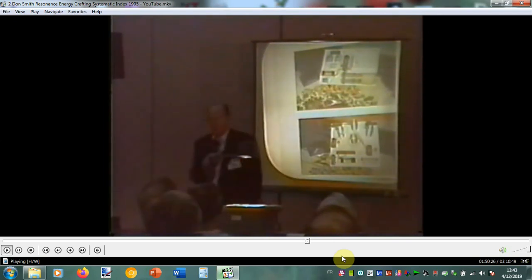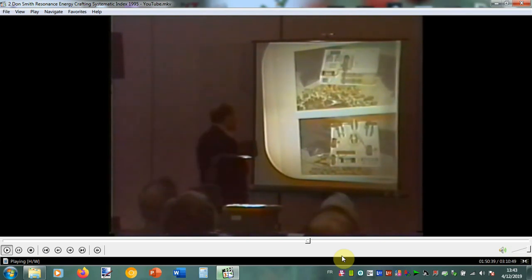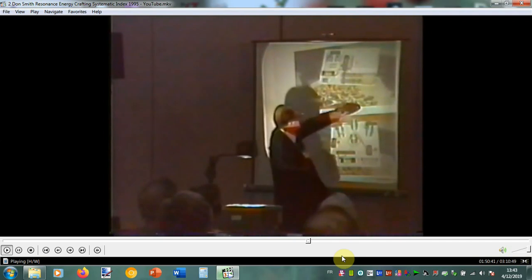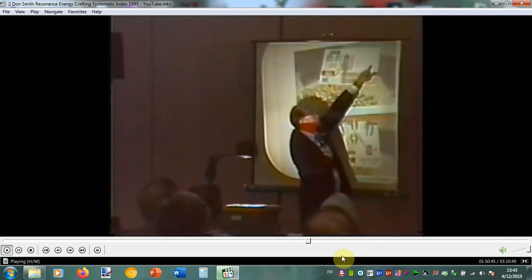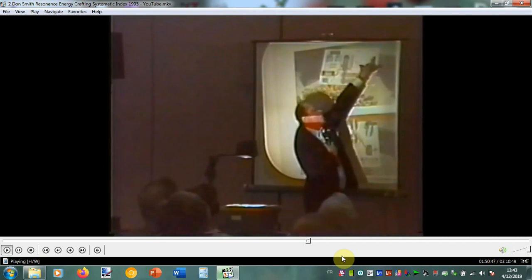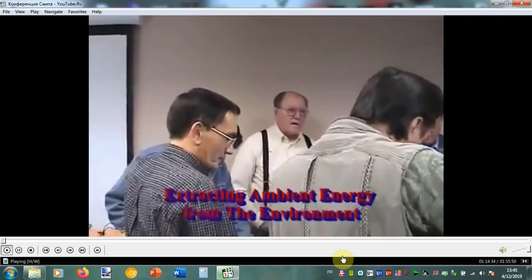That diode bridge is built on the underside of one half of a plastic case, it's a little box that you build electronic projects in. And coming out, what you're interested in here, this is going to be your plus DC, and this is going to be your minus DC. These are your two AC things going into the diode bridge.